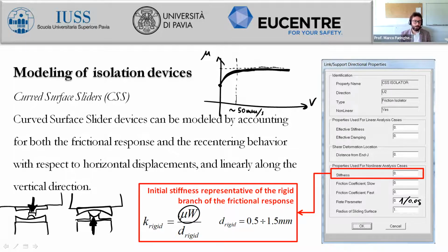And this could also be done by looking at the time instant where we have maximum displacement, and at that instant we can do a combination by adding some other load pattern. So we can define a load pattern by considering the new location related to the maximum displacement, and sum up the internal forces related to the time instant where we achieve the maximum displacement. That could be a strategy.